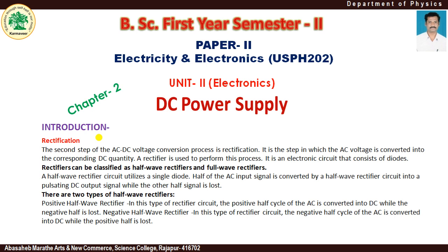The static or DC forward resistance of the diode is nothing but the ratio of instantaneous DC voltage to the instantaneous DC current, whereas the dynamic or AC forward resistance can be defined as the ratio of change in AC voltage to the corresponding change in AC current.